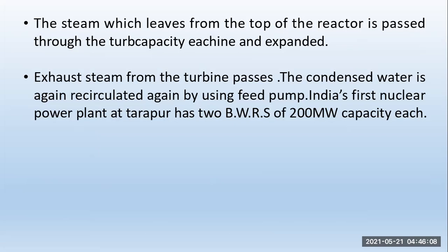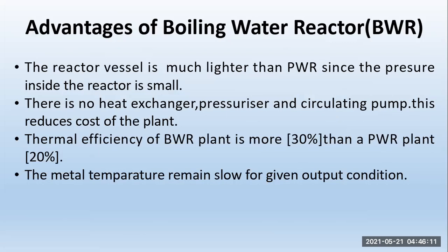Some of the advantages of the reactor: the water which is used as coolant, moderator, and reflector is cheap in first cost and available in plenty. The reactor is compact, and higher power density is the most distinguished feature of the modern pressurized water reactor core. A fuel loading of 190 tons can be made in a modern pressurized water reactor.